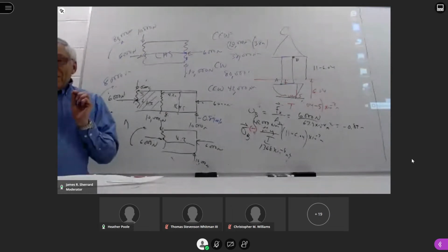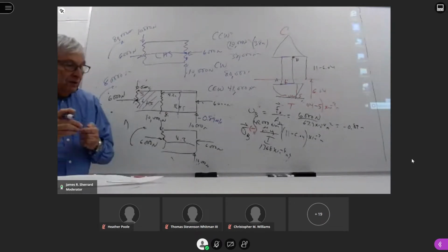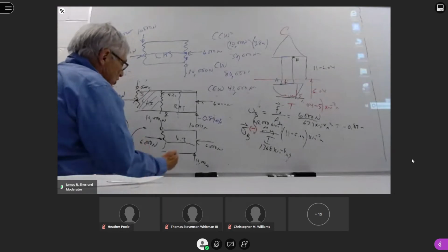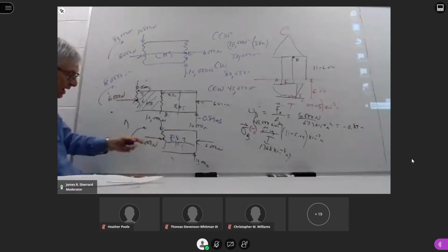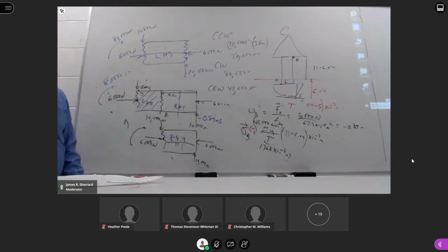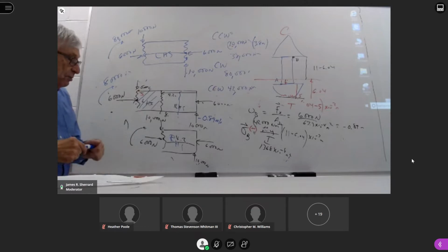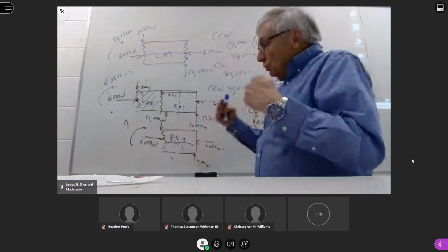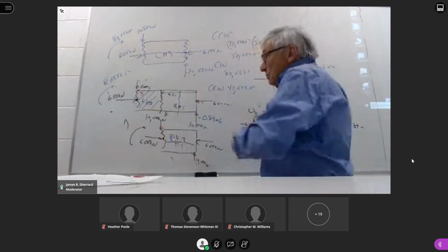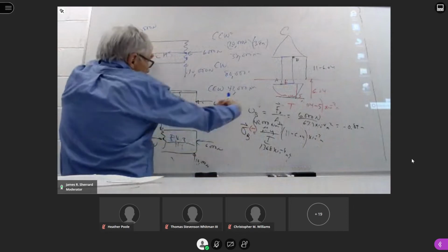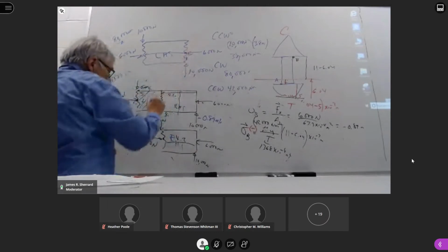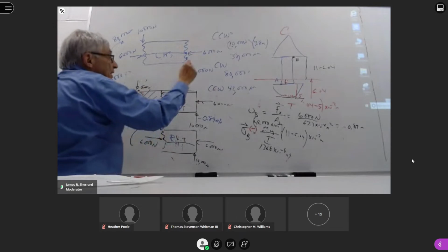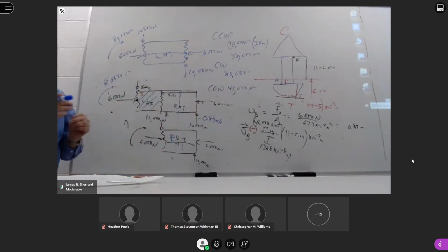Got it. Thank you. Whenever you do a free body diagram, remember the beauty of doing free body diagrams is we did it just looking at the right-hand side, and we came up with values at the attachment point. We just did it looking at the left-hand side, and we got values at the attachment point. The beauty is you can do it either way. You're still going to come up with the same numbers, but you always have a checks and balance, because if you take the left-hand side, take the right-hand side, and you join them back together to create your original cantilever beam, this cancels with this, and this cancels with that. It cancels out. If it doesn't cancel out, you've made a math mistake somewhere.